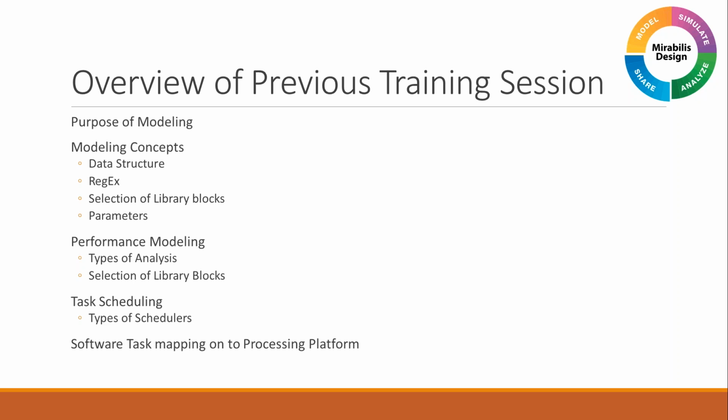This is a series of functions that are available in VisualSim that accelerate your model construction, plus also accelerate the speed at which your simulation runs. So say you want to look up the depth of a queue, rather than going and writing logic to create it, we have a function called getBlockStatus. Similarly, we're going to see some in this presentation as well, where we talk about getting access to data, modifying certain attributes inside the power table and things like that also.